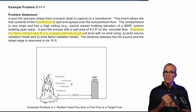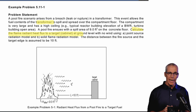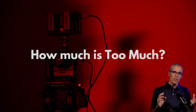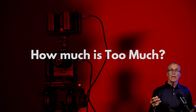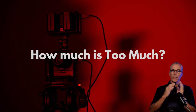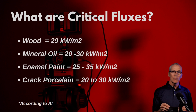So we're going to look at a transformer. Actually, the NRC did in their NUREG, and they calculate the flame radiant heat flux, in this case, to a nearby cabinet. The same kind of methodology will work for us. Now, we have to ask ourselves, how much is too much first? Because we can do all the calculations, it's pretty easy. You go to the spreadsheets, you figure out the square foot area of the pool, and you tell it the distance that you want. That's it, just the square foot area of the pool and the distance, and it calculates everything else and gives you this heat release rate flux across an area. So how much is too much of that flux?